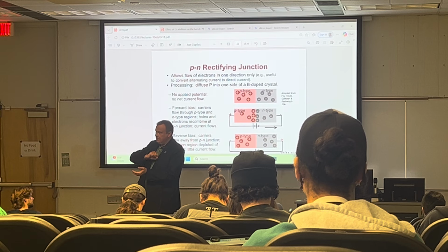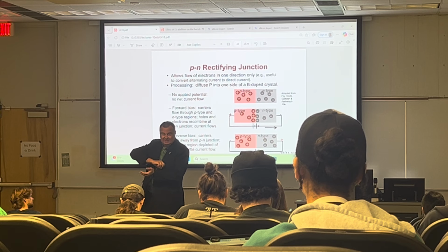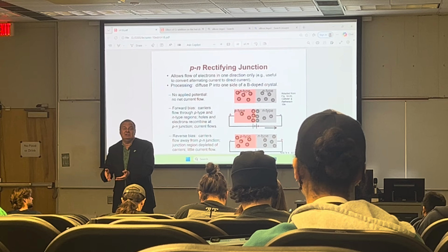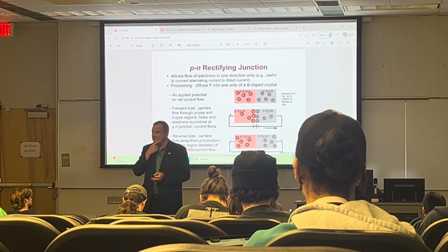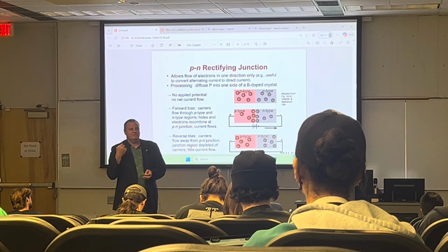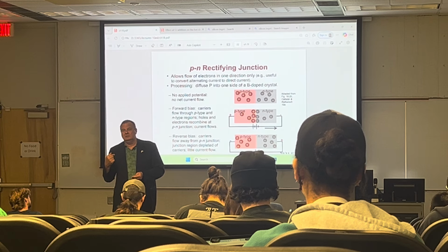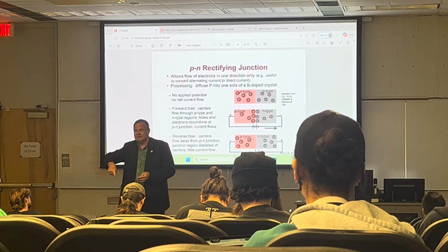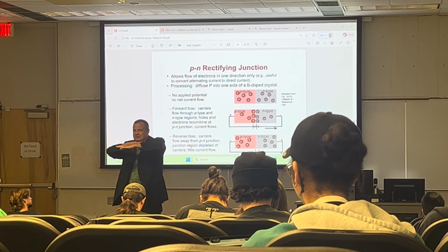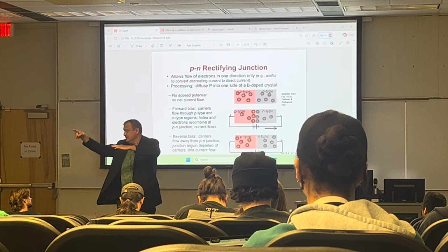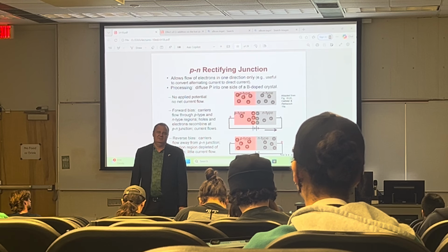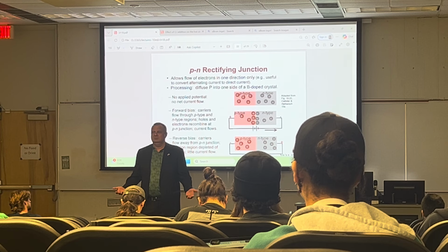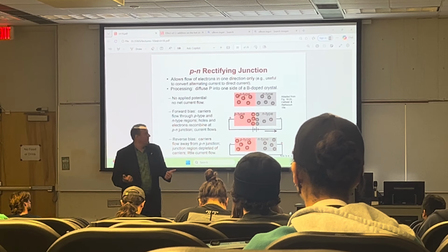And what you're doing is you're pumping the current only in one direction. Okay? So with just one simple diode, which is a semiconductor device, you can do a conversion from alternating current to pseudo-direct current. Because it goes plus and minus, you chop off the minuses, see? And you only get the pluses. And because it is 60 times a second, it's kind of like steady flow, almost. So I just explained to you the physical principle of a diode and converting AC to DC.